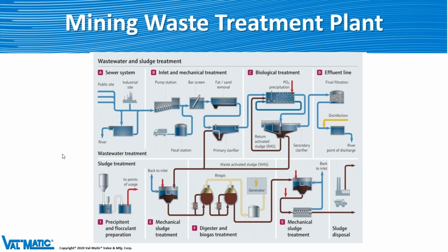So if some guy is saying, well, I'm having problems with this equipment down from the pump or whatever, and I don't know how to fix it, then the question would be, do you have an air valve? If you're having problems around a pump, or down away from a pump, or on elbows, or after some kind of equipment, look and see. You might have to put an air valve in that particular slot to be able to get the air out, so you have more flow and fewer problems.